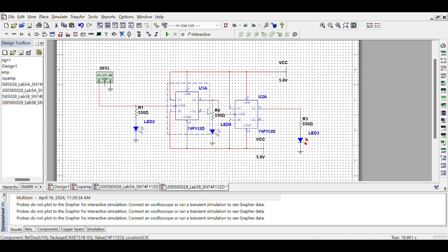Basically, the speed of this turning on will be half of what this was. So essentially, we can step down the speed of each of these LEDs and their flashing, and control that using the JK flip-flop here. And so in this configuration, we'll go from, let's say, 100% speed to 50% speed to then 25% speed, because it's halved again after this one.